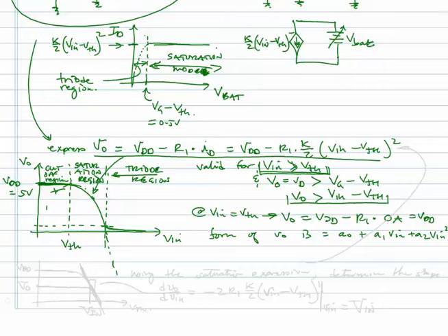As this takes a dive, if we were to position ourselves at some operating point right on this transition curve, at capital Vn and capital VO, and then put in a small perturbing input signal around there, the small output will be the small signal input times the slope of that curve at that operating point.